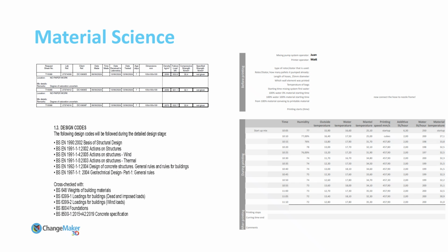We then recommend that the manufacturers of the materials are consulted and that data sets are used from UKAS accredited sources. This enables the designers and the engineers to have a baseline position of the material performance from which they can apply their factors of safety and undertake finite element analysis. On the screen in front of you, you can see cube test results